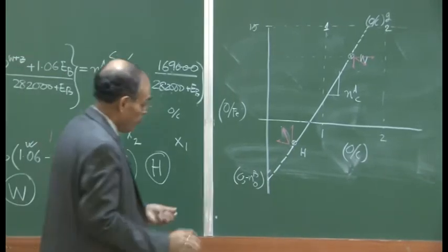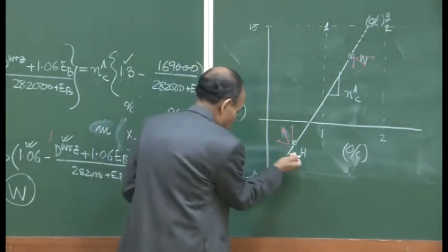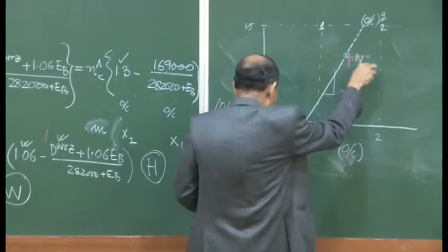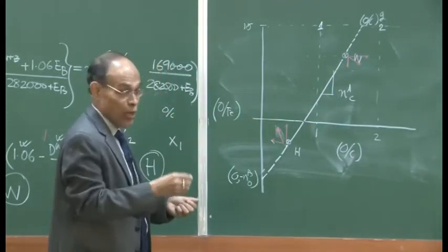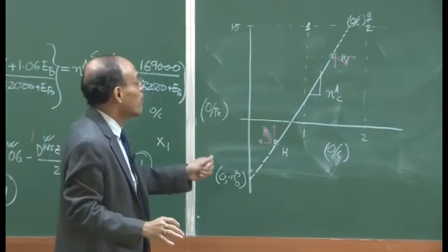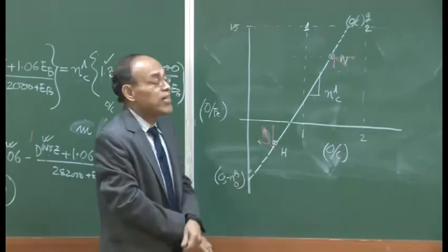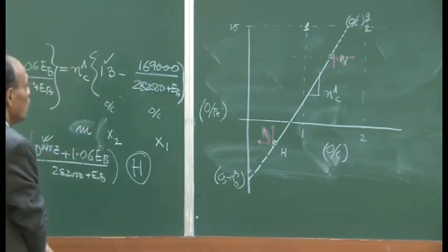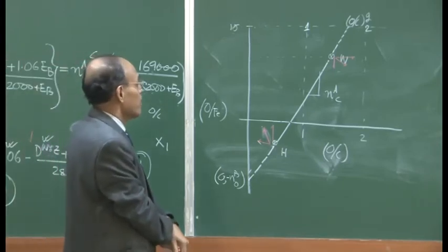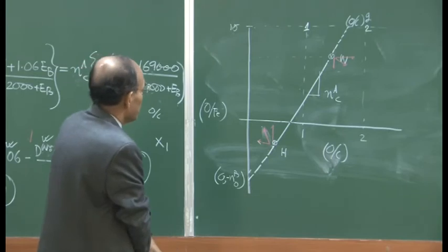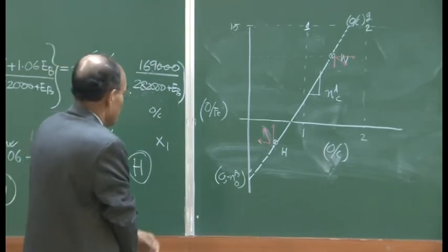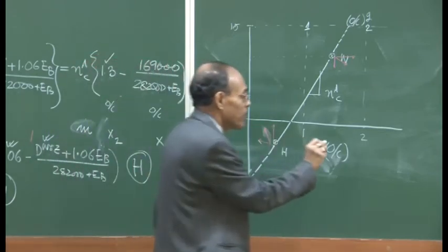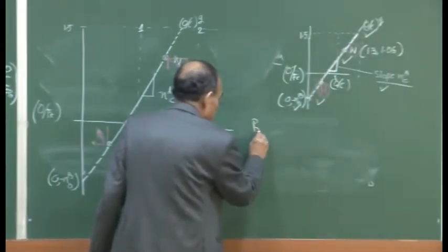If you ensure that the H point moves in these three plausible directions, or the W point can be made to move in these directions, we are going to generate, in brief I can say, a less steep line, essentially meaning that we will have less coke rate, more carbon dioxide in the top gas mixture, and therefore a smaller blast rate. You remember the definition of productivity I have introduced.